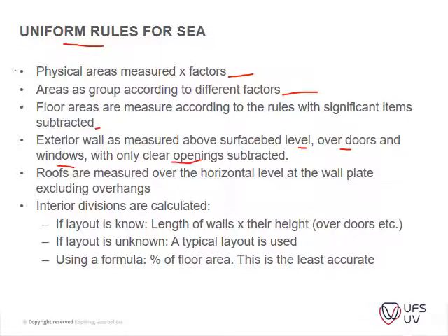Okay, so the rule of thumb is you measure your walls over the doors and windows, except if it's a substantial opening. Okay, that is a relative term, and I think you would ask the question, but when is it a big enough opening? The rule of thumb is usually when you have sliding doors, windows, that type of openings, and that's more than a standard double door opening.